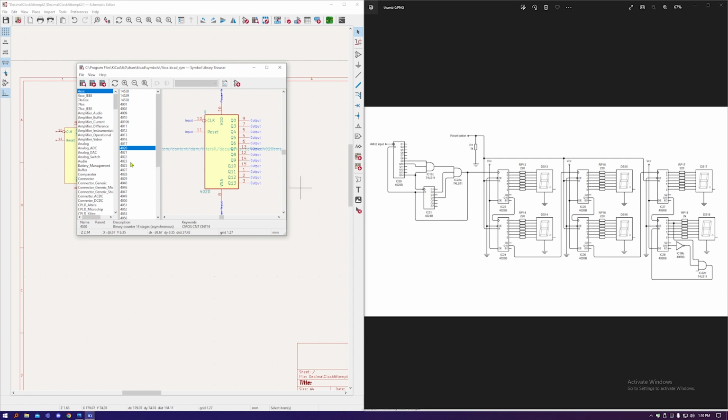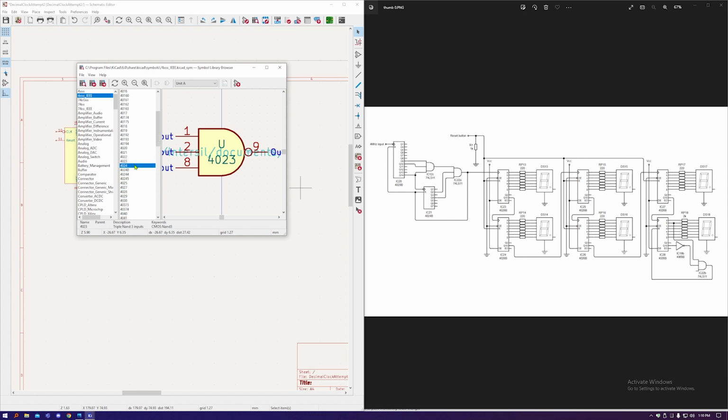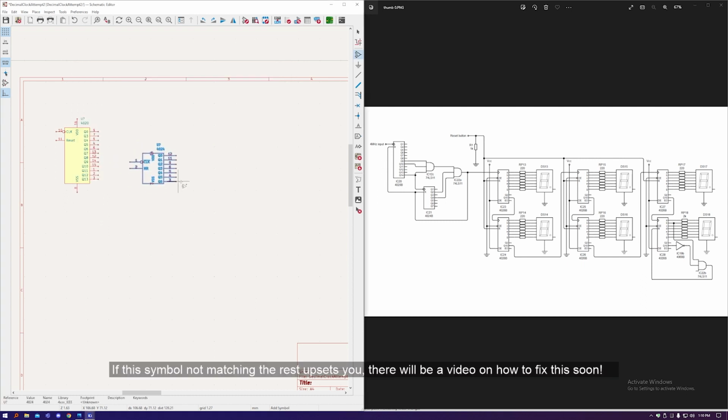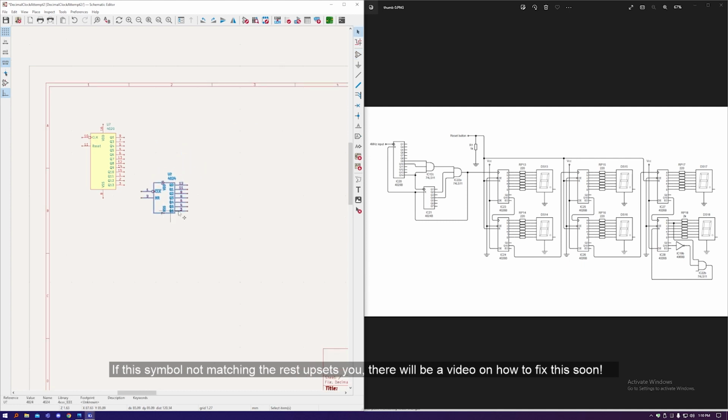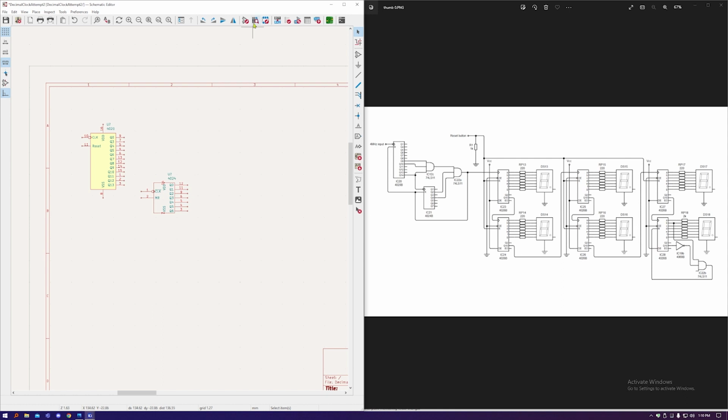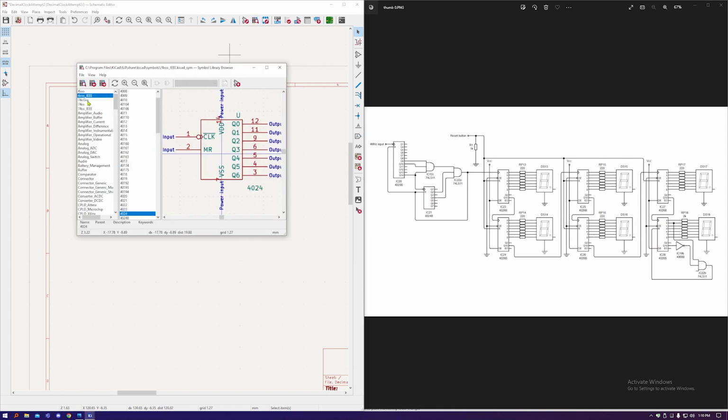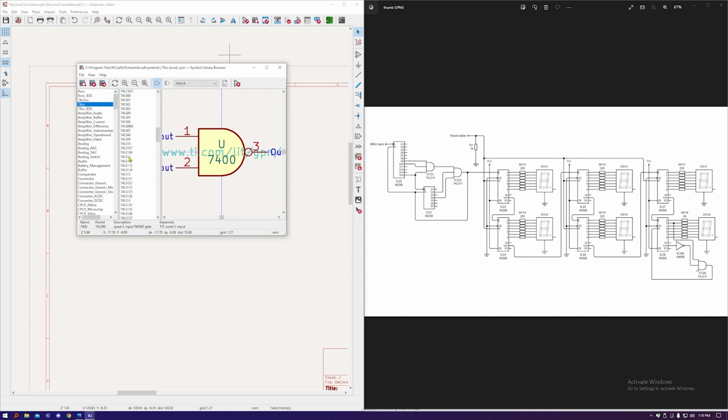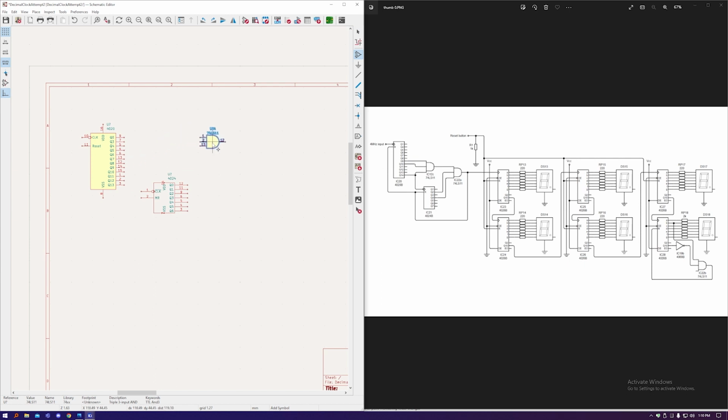Then click on here again. We want the 4024 next, which unfortunately isn't here. But if we go to this, which is some more 4000 series chips, it is here. So we'll click on that. Next, let's look for the 74LS11. You can see 74's just below. 74LS11. Now, these are quite interesting when we add them. So you can see this is a 3-input AND gate, like what we have on the right. And when you click, you then have another one, and then this is power to the chip that contains those 3 AND gates. So for now, we'll just move the power out of the way.